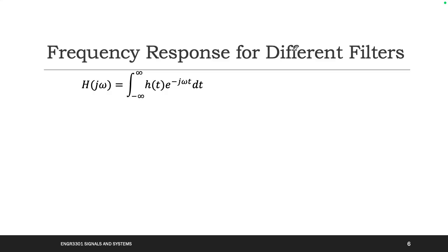What does that mean? Which means you multiply by zero here, multiply by zero here, and then you just remove these and get this one, multiply by one here, am I right? That makes sense to you? And then if you have a band pass filter, you just want this one, you don't want this one, you don't want this one, which means you multiply by zero here, zero here, and one here. And the high pass filter is similar: multiply by one here for the one I want, and zero for the others. That makes sense to you? Yeah.